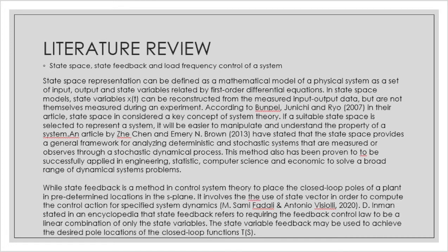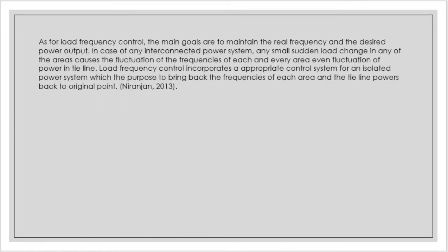Meanwhile, state feedback is a method in control system theory to place the closed loop poles of a plant in predetermined locations in the S-plane. It involves the use of state vector in order to compute the control action for specified system dynamics. As for load frequency control, the main goals are to maintain the real frequency and the desired power output.